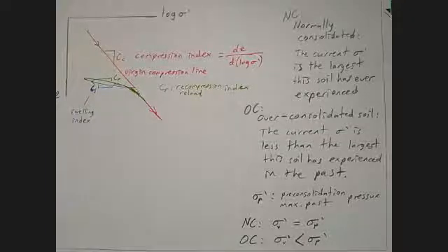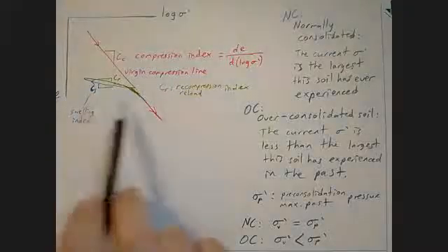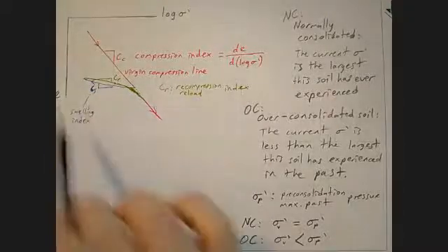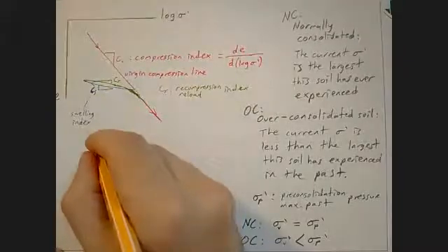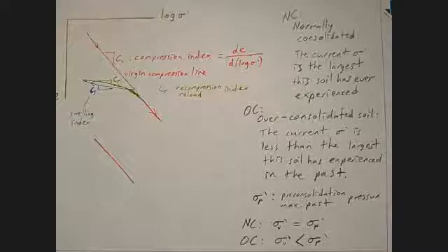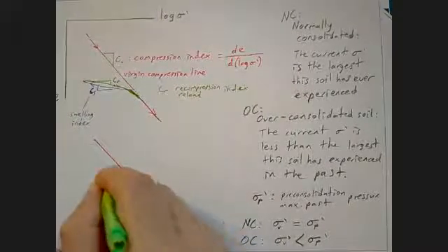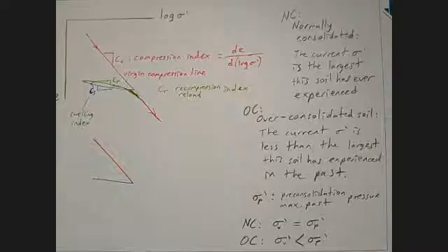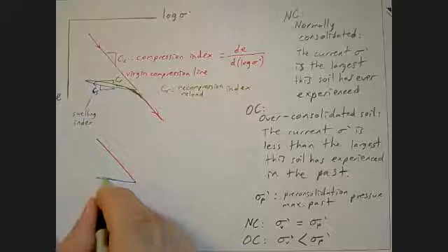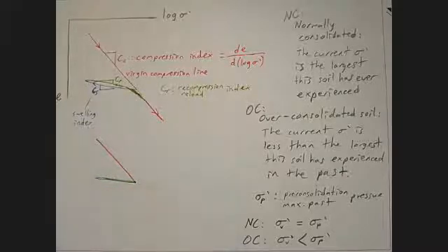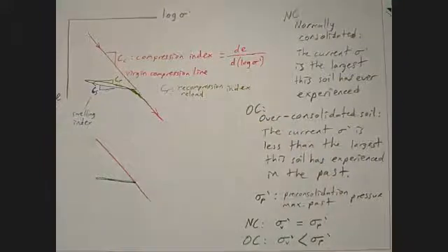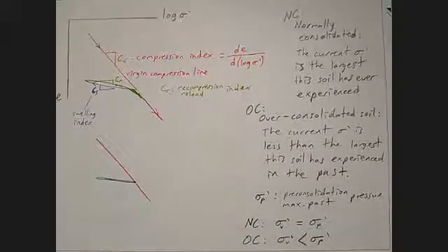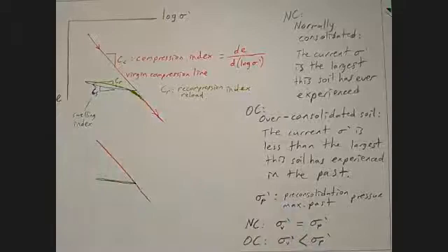Now, first of all, from this point onwards, I'm going to idealize this behavior, this curvy bit, by drawing it like this instead. So it can have a line here. Then if I unload, it goes like this. And if I reload, it will come back on the same line. And then it will continue from here. So I'm going to ignore that curvy bit because it is much easier to do calculations with just lines, and it is not going to be a significant source of error anyway.